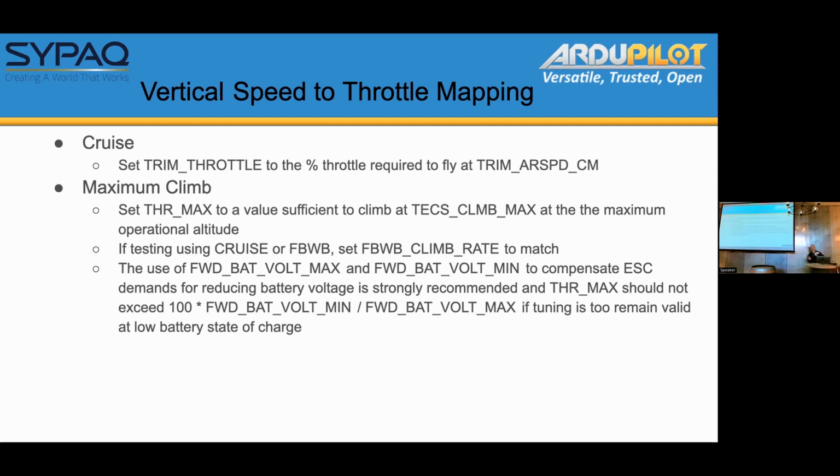Then when you level off, you may have excess throttle, and it's got to raise the nose to reduce the speed, and you end up wondering why the transitions between climb and level and descent and level don't look appropriate.